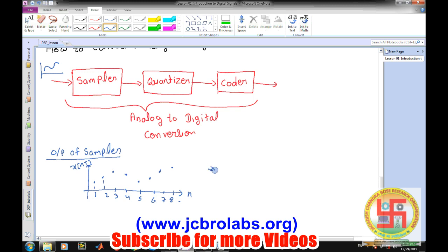So here we come to the concept of the sampling frequency. Let's say we have a sampling period of 1 millisecond. That means this represents the 1 millisecond instant, this represents the 2 millisecond instant, this represents the 3 millisecond instant, and so on. Generally it is represented as NT when we convert the signal, or for easy configuration we represent N and define separately what T is. Now this T is the sampling period,